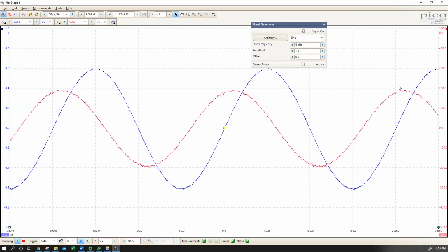So that right there demonstrated the high pass nature of this particular circuit, where I have my load in series with a capacitor. So I went to a higher frequency, and now the fraction of the total circuit voltage that's dropped over my load increased. So more voltage is effectively being passed to the load, hence high pass. So that concludes our high-low pass spectrum analysis, and then with a little finish going back to our time-based oscilloscope signal with our capacitive-based high-pass filter circuit.